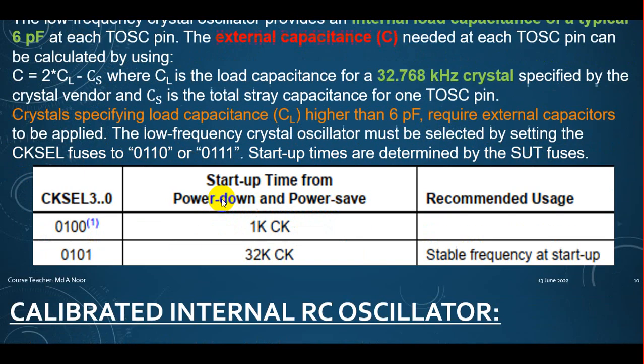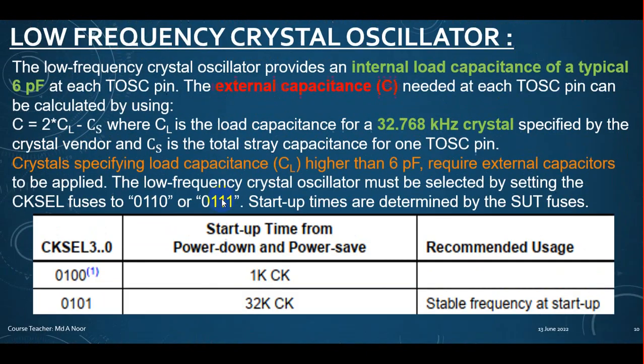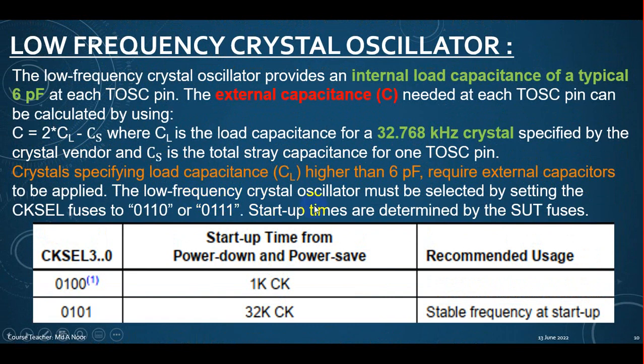Okay, the low frequency crystal oscillator must be selected by setting the clock select fuses to 0110 or 0111. Startup times are determined by the startup time fuses.